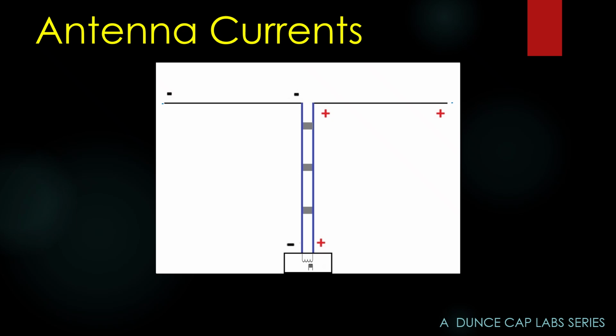Oh, look at the tuner. You might notice my tuner is a link coupled tuner. There's just 2 big coils and some capacitors in there, and one of the coils feeds the line and switches each pole from positive to negative as the sine wave progresses. Now, some tuners have a toroid core feeding the line, but electrically it would look the same. All right, so what happens when one side goes positive, the other side goes negative, is you get current flow.